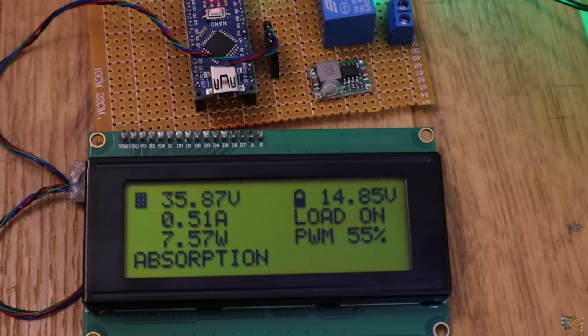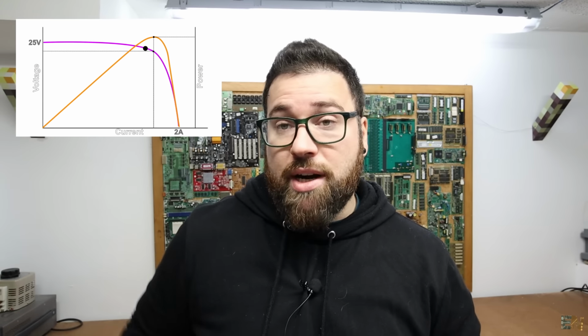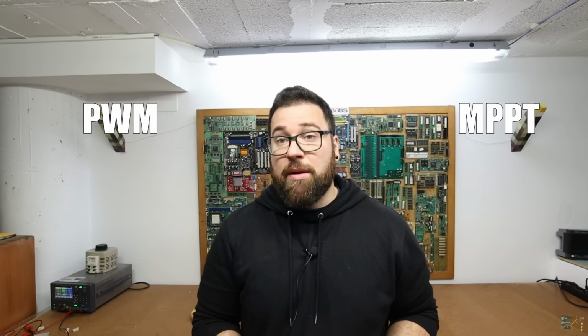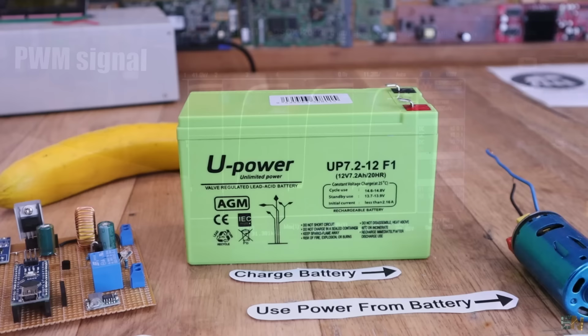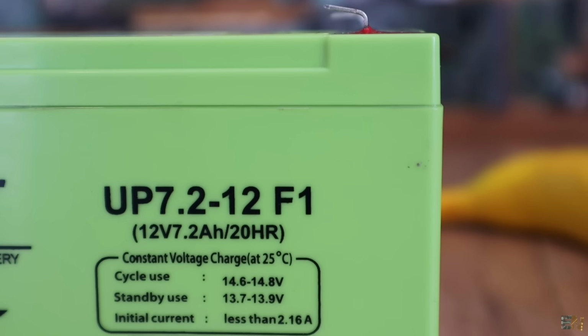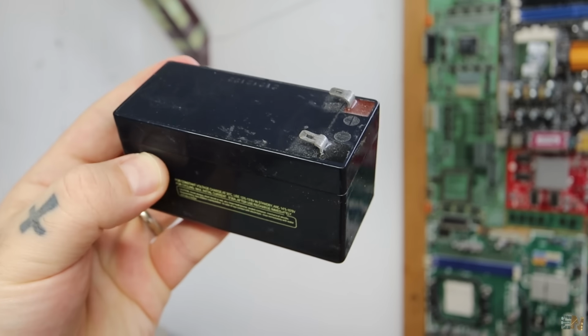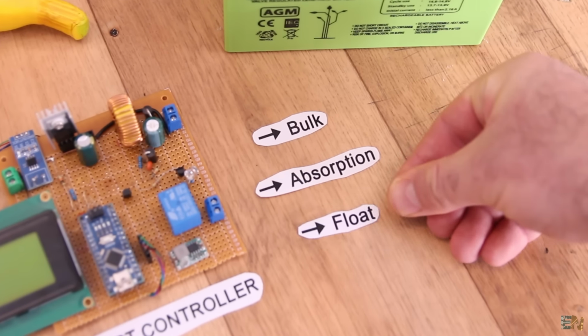That's what the MPPT will do anytime you connect a variable power source and then connect it to a battery to charge it. Another thing I have to explain is the difference between MPPT and PWM controllers, which basically set the voltage of the battery, in this case for example 12 volts, and then measure the current and change the PWM output in order to gradually increase the current, because some of these batteries have a specific charging process with the bulk, absorption, and then the float state. That's what I did in my previous MPPT power controller.